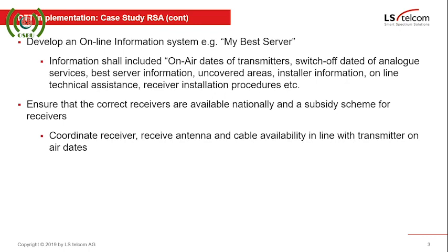And then what we found, we simplified the process by not using channelized antennas anymore, but using one antenna that can be used for any part of the band. Nowadays it is simpler because most of the countries only use up to channel 48 or 694 megahertz from channel 21 or 470 megahertz for the transmissions.